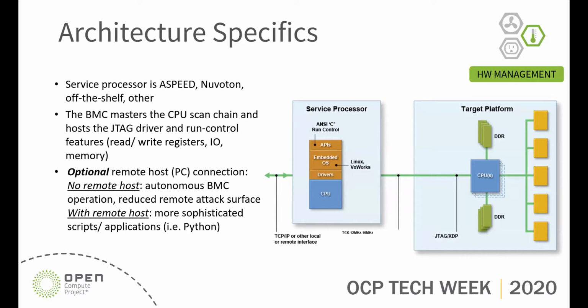So let's look at that in a little bit more detail. Service processors or BMCs, certainly not limited to OCP platforms, but service processors of any type, ASPEED, Nuvoton, off the shelf. Implementations have been done with Microsemi SmartFusion parts, anything that can accommodate a fairly small footprint, a 100K, 200K implementation to provide the JTAG driver and the run control firmware.